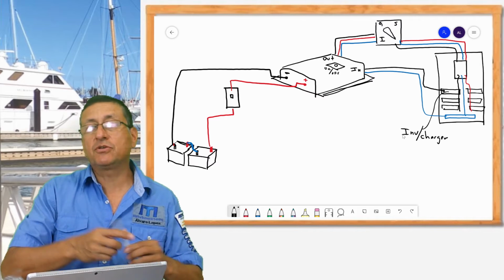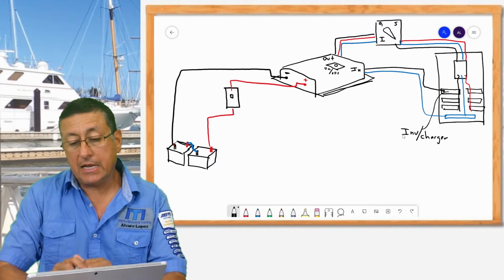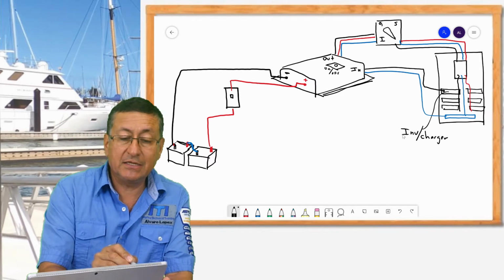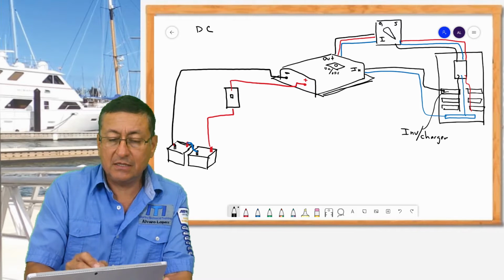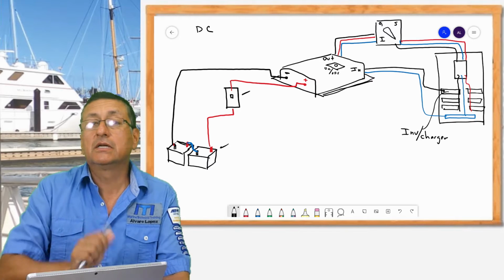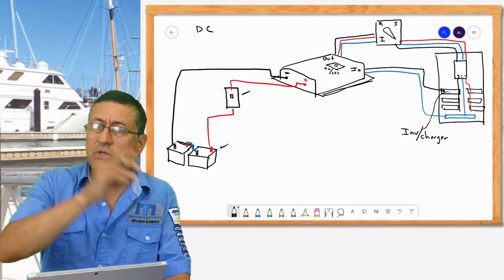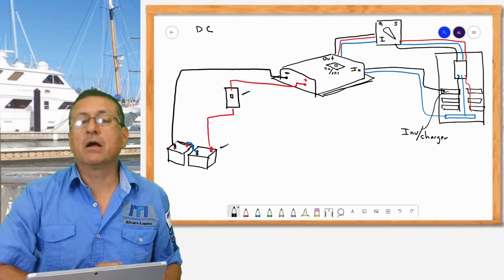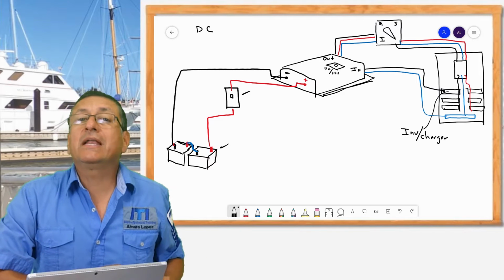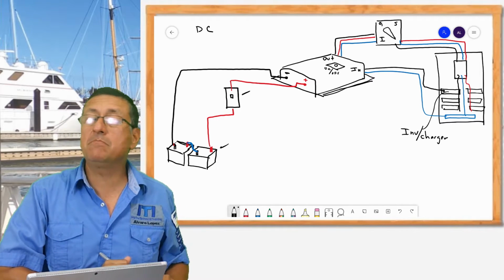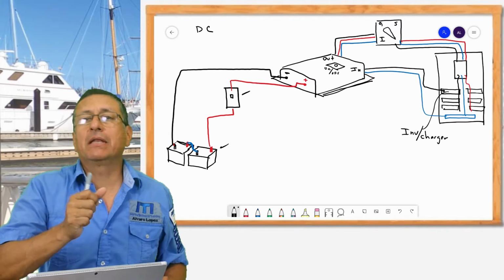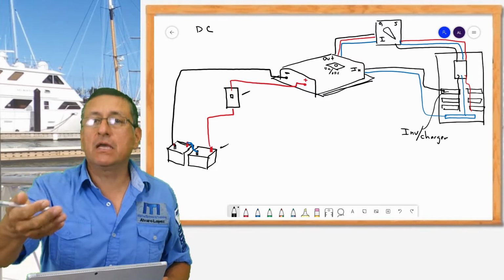I have a picture that I prepared, and in that picture I connect an inverter. This is the DC side, and this is the negative and the positive, the group of batteries, and this is the main breaker to activate the inverter. Check with your instructor, in the marine inverter that they have in the lab or on the boat, where is the DC main breaker at the input of the inverter? This is the breaker used to activate the inverter.